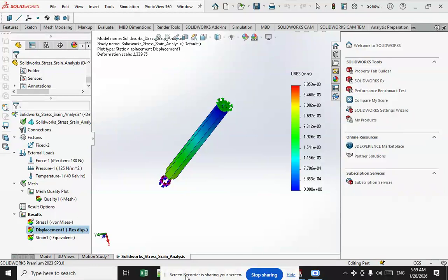Even under the assumption of linear elastic behavior of the material, the relation between the stress and strain tensors is generally expressed by a fourth-order stiffness tensor with 21 independent coefficients, a symmetric 6 by 6 stiffness matrix. This complexity may be required for general anisotropic materials, but for many common materials it can be simplified.